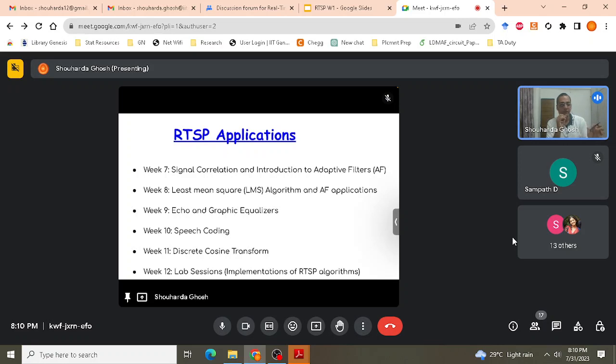Now 127 and 128 can be represented as an 8-bit number, so you're taking 8-bit registers. We'll talk more about registers soon. 8-bit registers mean more area. But you see my data is oscillating between 127 and 128. So what will happen if I subtract 128 from the entire data stream? It's just zeros, plus ones and minus ones, right? So based on how correlated the nearby data are, you can compress the data. That's where compression comes into the picture with correlation.